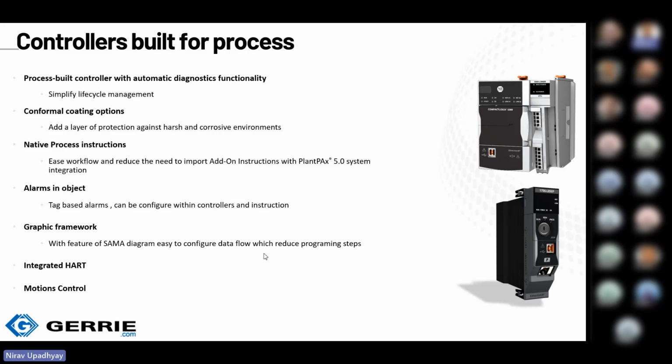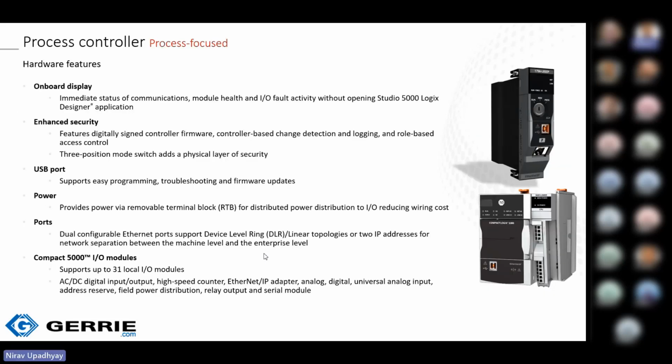Integrated HMI, motion control, and an onboard display. So you get the status of communication, module health, and IO fault activity without opening the Studio 5000 Logix Designer application. Enhanced security with digitally signed controller firmware, controller-based change detection and logging, rule-based access control, and a hardware 3-position mode switch that adds a physical layer to it. USB support for ease of programming, troubleshooting and firmware updates.